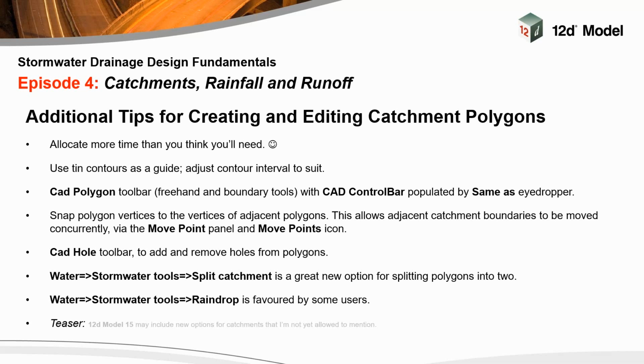My general tips though would be to use the tin contours as a guide and adjust the tin contours via the view settings to suit your particular job. Use the CAD polygon toolbar. The freehand and boundary tools are very good within that for drawing polygons, and populate your CAD control bar using the eyedropper. If you don't know what that means, I can show you, but I am running over again.